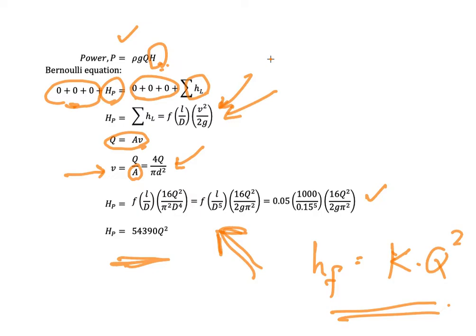As I explained in chapter 2, when we are dealing with a pipe system with a larger diameter, sometimes it reaches a fully turbulent condition where the increment of velocity and Reynolds number does not change the friction, not change the value of F. So the value of F is fixed or constant.